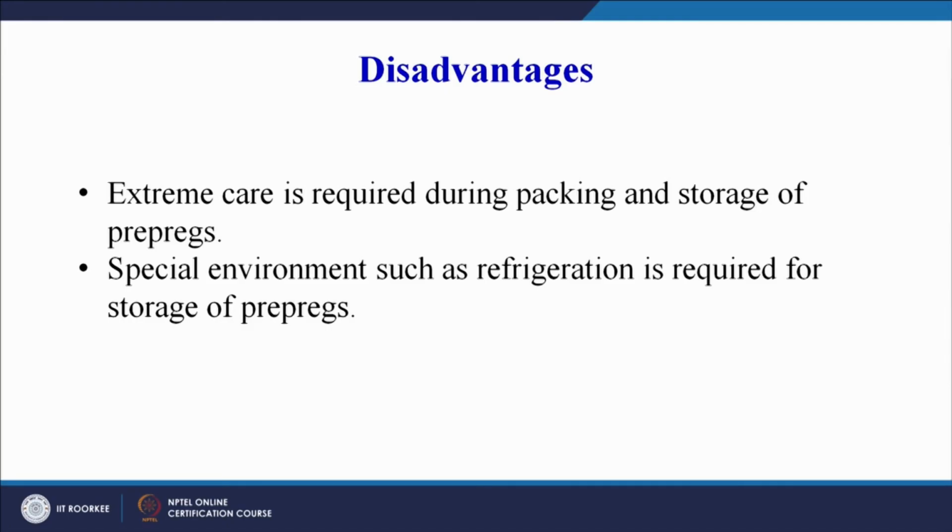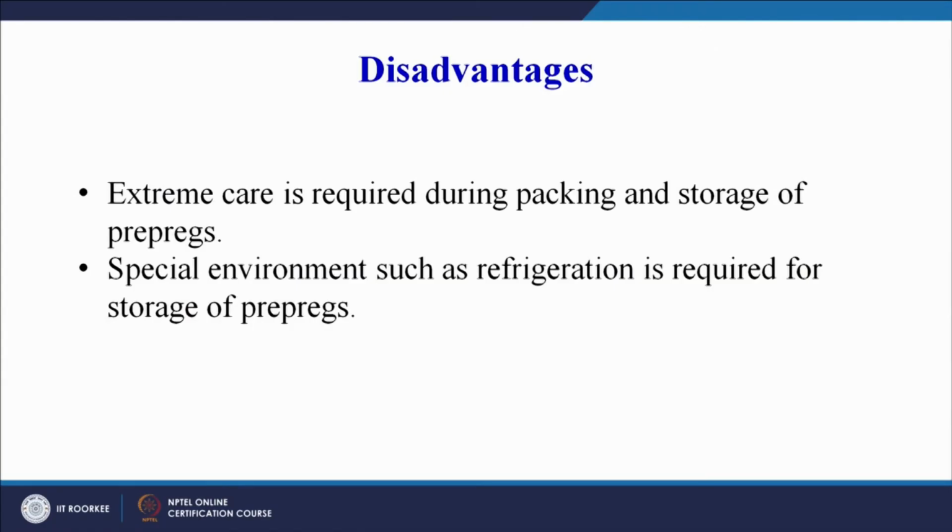What are the major disadvantages? Extreme care is required during packing and storage of the pre-pregs. I think this is the third or the fourth time in today's session only that again we are coming to the same point, that storage of pre-pregs is one of the major limitations. Special environments such as refrigeration is required for storage of pre-pregs.